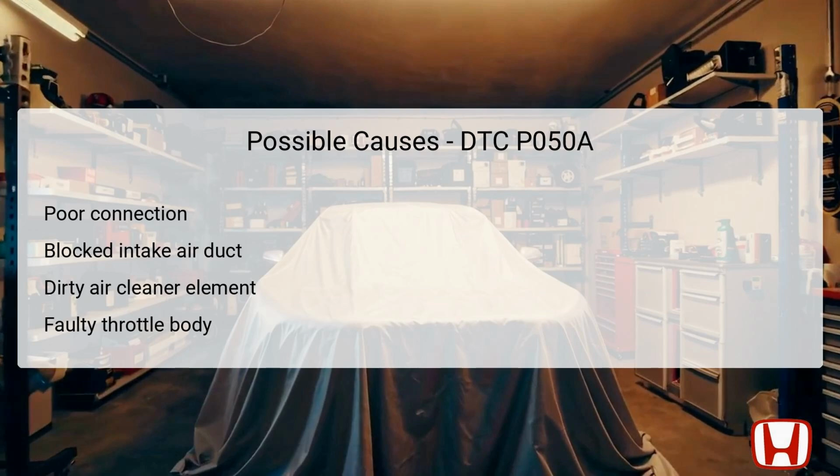Another critical area is the throttle body. If this component is faulty, it can cause chaos in airflow and idle stability. Issues such as dirt buildup or mechanical failures of the throttle body can severely affect the engine's operation during cold starts, which ties directly to how the system regulates idle speed. In summary, several interlinked issues can prompt this DTC, necessitating thorough inspection in each area.